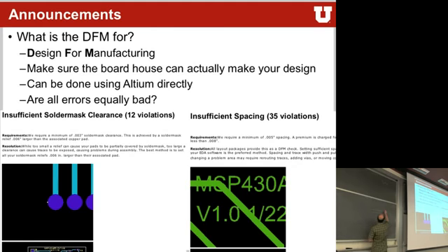Now, if we have a hole somewhere that we want to solder to, you preferably want the solder mask to stop before the hole. Or else, it could happen that the solder mask goes on top of the hole and it does something like this. And this is not very good because this can then lift off and the solder mask can come off, and they don't want that. In addition to that, you now have this gap that you have to fill with solder, and sometimes you have to go inside of it, also not very good.